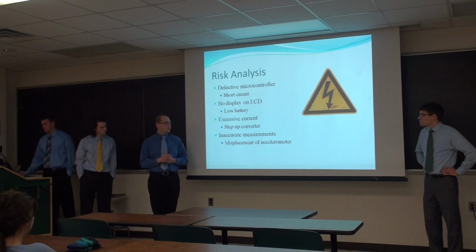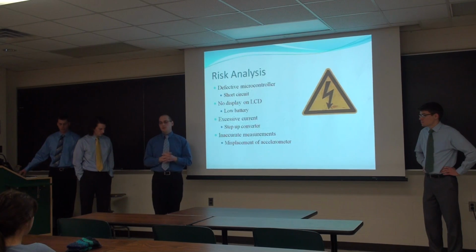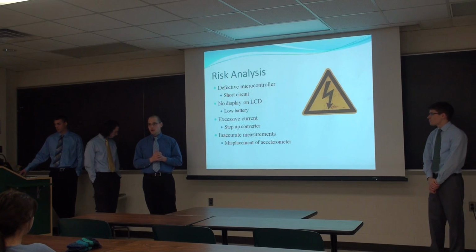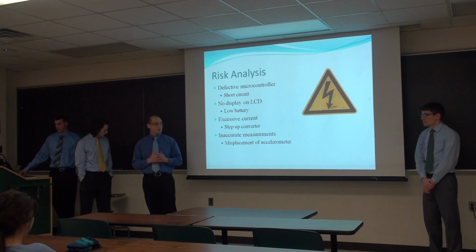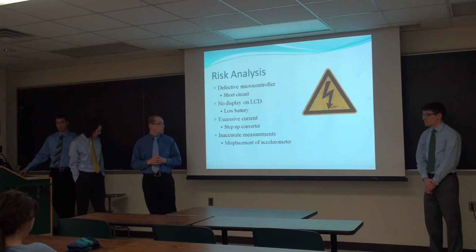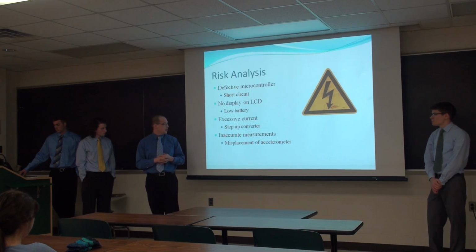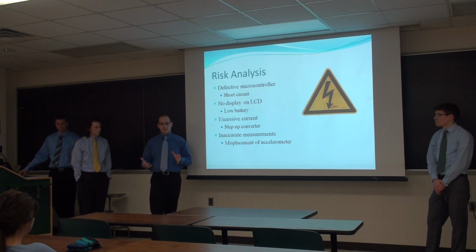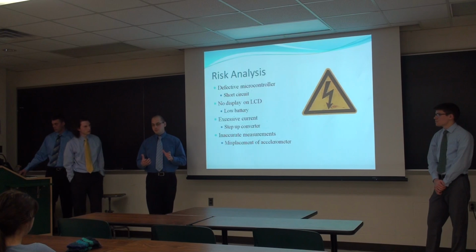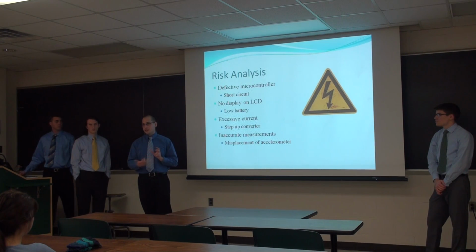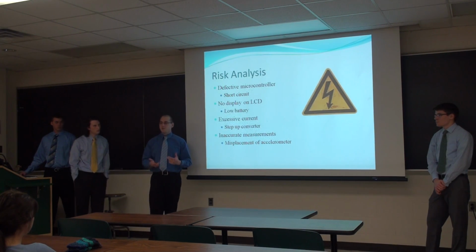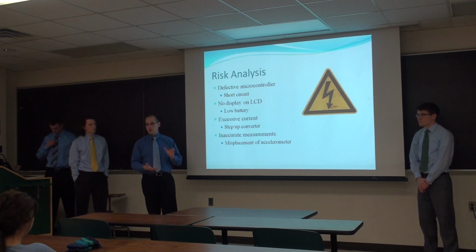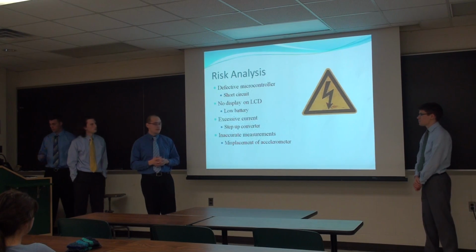We have excessive current. Since we are using a step-up converter, if we do not put this together right, we could have anywhere between 50 and 100 milliamps that we don't want, which, as we all know, could be dangerous. It could actually drain the battery faster or even hurt any other circuitry. And we have inaccurate measurements. Like EJ said, we have single axis. If you want to measure the x-axis, you have to make sure that the meter that you place is in that correct axis. If you want to measure all 3, you need to have 3 meters. If you were to place it somewhere on an angle between the X and the Y, you would not be able to get clear measurements, so usually it's a user error, so that's pretty low.